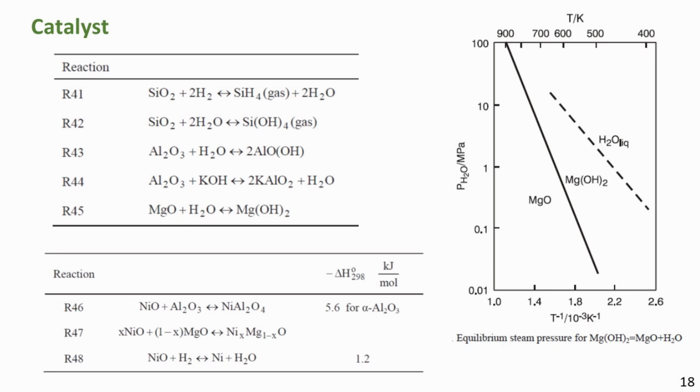Typical reactions between nickel and support are listed in another table. At steaming conditions, at high temperature, formation of the blue nickel aluminum spinel may start at temperatures above 700 degrees C. A similar trend is observed for the reaction between nickel and magnesium oxide.